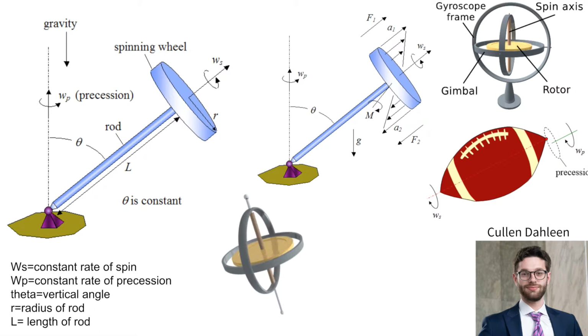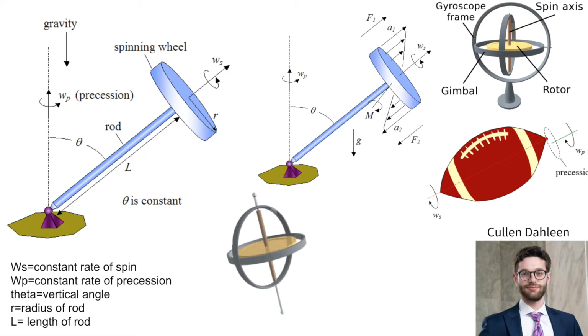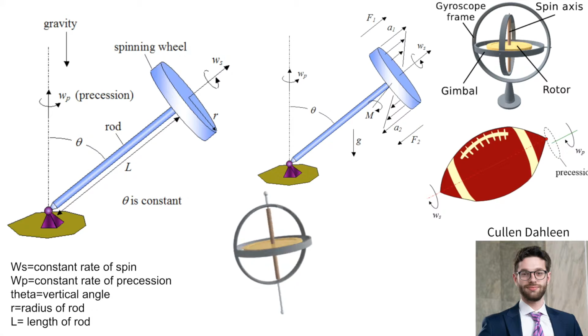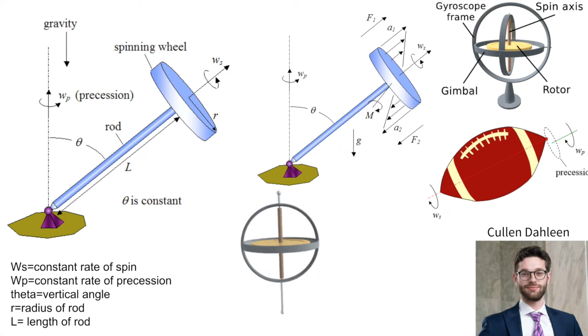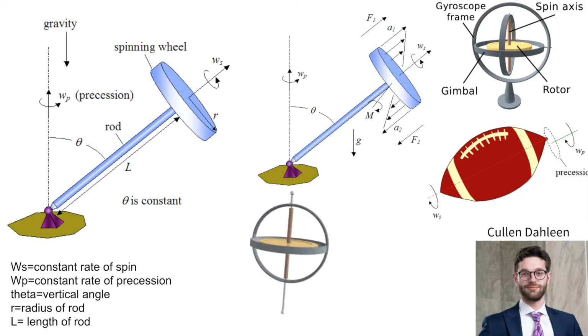Gyroscopes are mechanical devices with applications throughout the aerospace industry, and are most easily defined as a wheel mounted in 2 or 3 gimbals. The axle of the spinning wheel defines the spin axis, and this wheel responds to an applied force by a reaction force to the output axis. An example of this is an attitude reference gyroscope, which is a gyroscopic flywheel with free-moving output gimbals, and is commonly used in aircraft and spacecraft for pitch, roll, and yaw outputs.